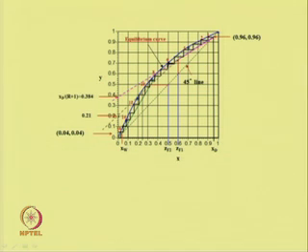So, from this point we can draw the operating line of the intermediate section, and we know the feed conditions over here at Z f 2, and it is a saturated vapor. The q line equation is this. So, this is the q line for feed 2. It intercepts over here. We can now join the operating line equation for the stripping section.